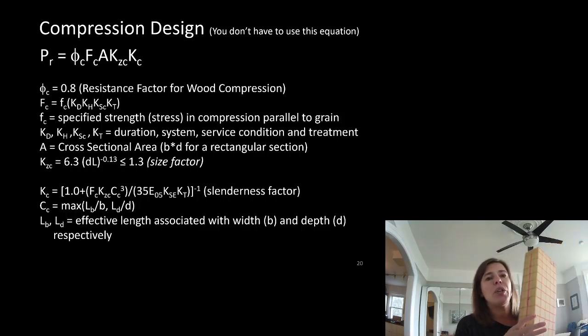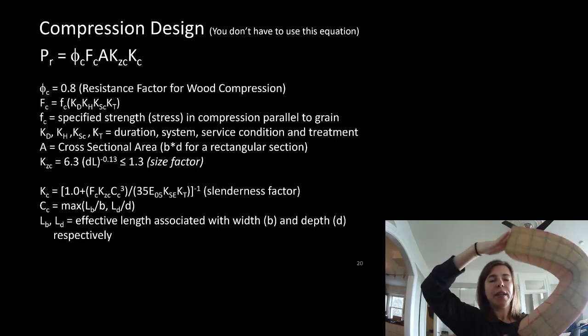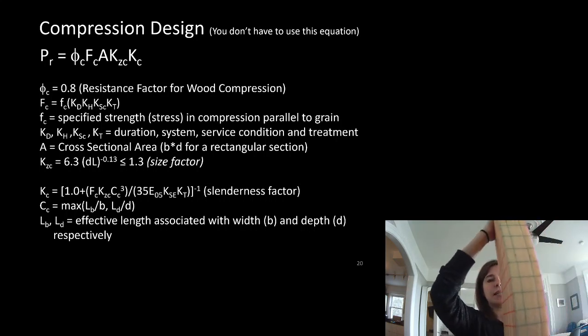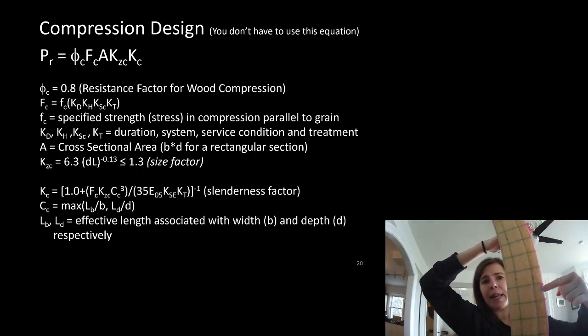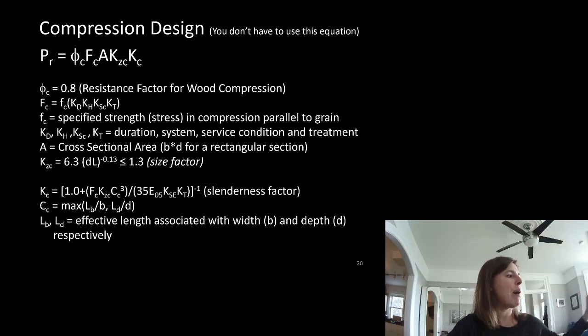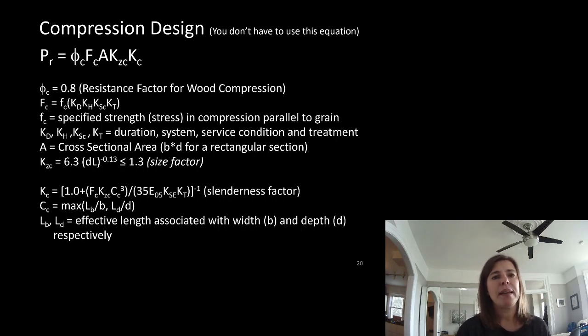Now, what we do with steel, it's pretty obvious. If you look at this, when I try to squash it, you can see that it tries to buckle in the direction of the thinnest dimension. Pretty obvious. But if I just put my finger right here and I don't do much to it, it's really hard to get it to buckle now. Remember our decks or our joists on our steel stopping it from buckling sideways at the top? Same thing. It does not take much to stop it from buckling.